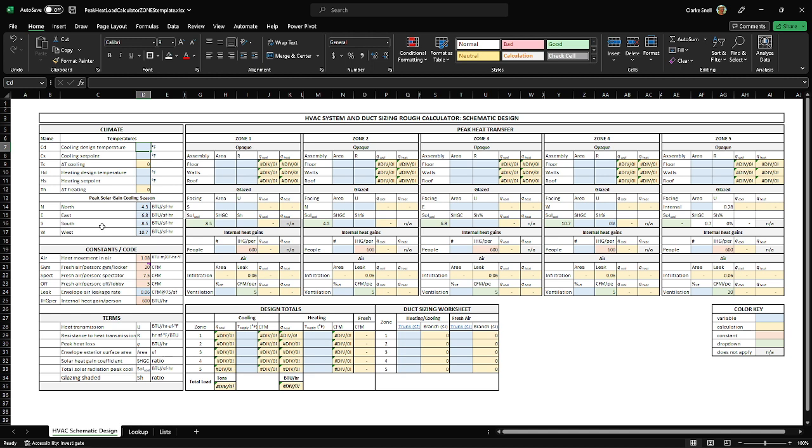If you have a 0.04% design temperature, that means whatever number you type in there for your climate, only 0.04% of the time is it above or below that temperature, based on whether you picked a cooling or heating design temperature. So we're not even doing that right now. We're just picking a number and saying we're only designing our system up to this temperature.